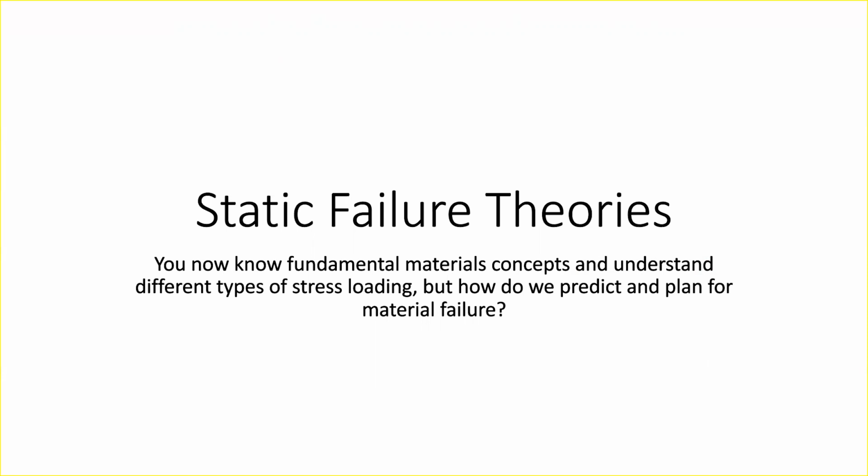This is something called a static failure theory. The idea is that I have a description of my stresses for a given material, so how do I describe if it fails? It turns out the answer to this is really complicated. It's not just dependent on the stresses, it's also dependent on what kind of material you have. If you have a brittle material, the failure you'll expect is very different than if you have a ductile material. So there's no one encompassing theory that describes all of this. These are approximations that we make to predict the failure based on empirical testing of these parts.